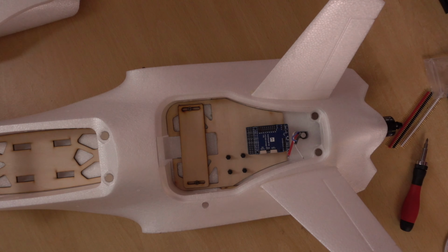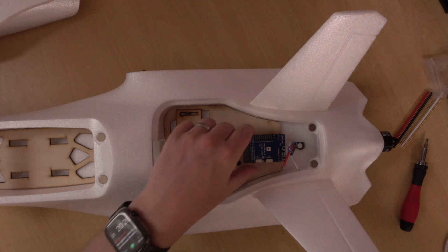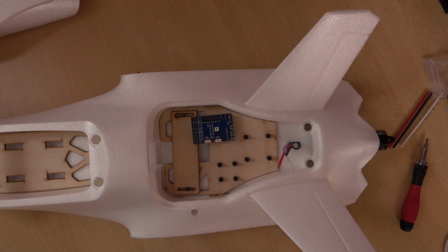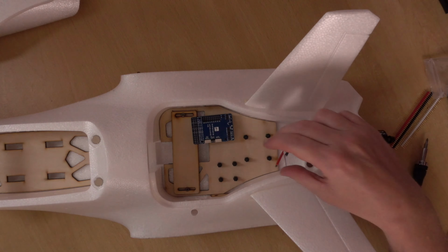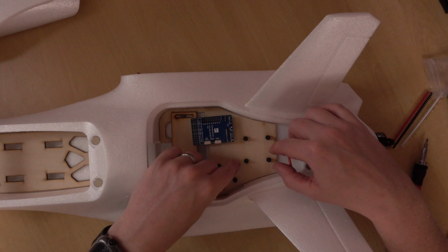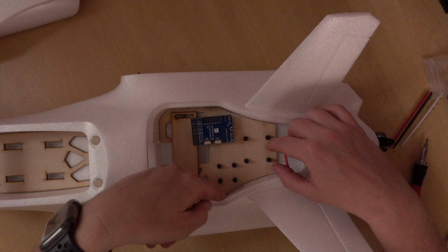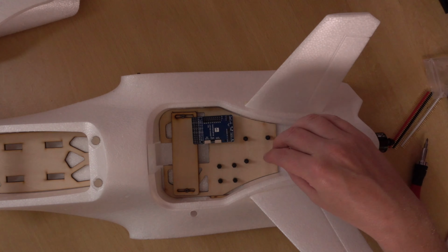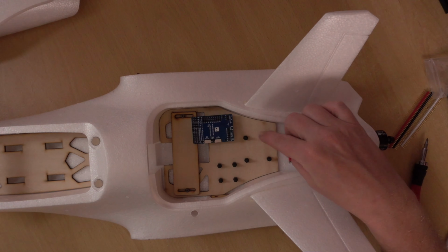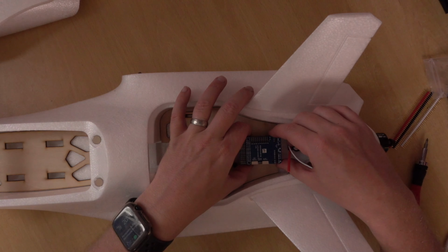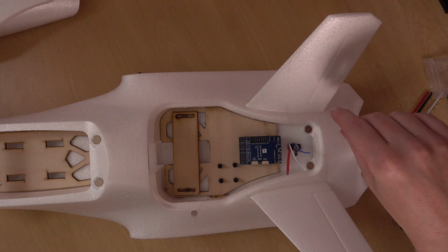for the beginner series. So the first thing that I'm going to do is actually rip these standoffs out. It would be much better if we had the option. So all 8 of these standoffs are going to come out. I don't really see the point of having them anyway because it blocks that screw off, but also I'm not going to be putting anything on there. For a 30 by 30 flight controller stack, that's not a bad idea, but with this particular flight controller and most other wing controllers, that's not going to happen.